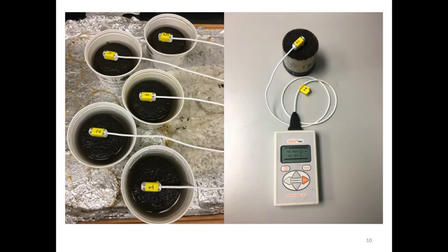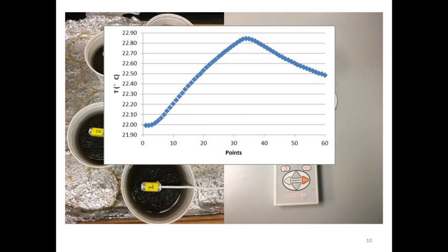With the sensor inserted vertically in a soil core, a heat pulse was applied to the heater, and 60 temperature readings at the temperature sensor were recorded. All three soil thermal properties were derived from the temperature response curves.